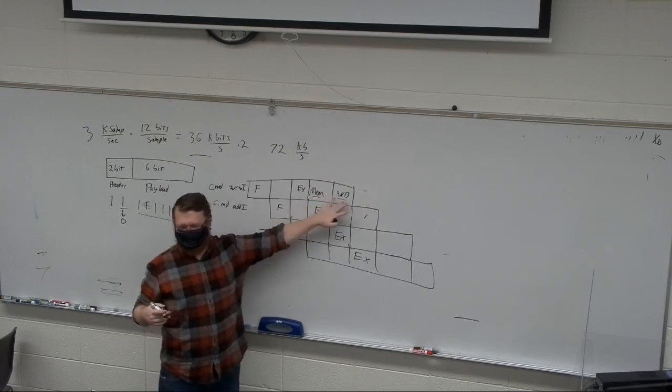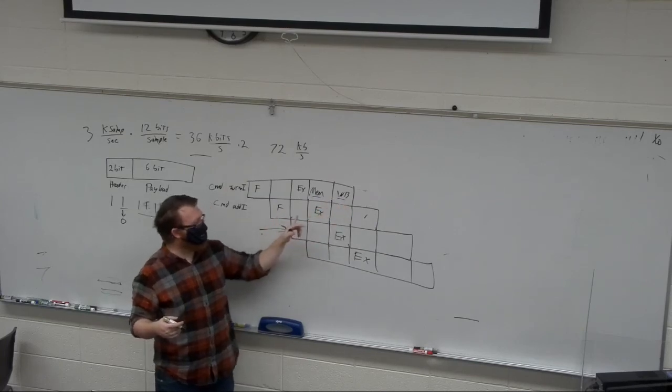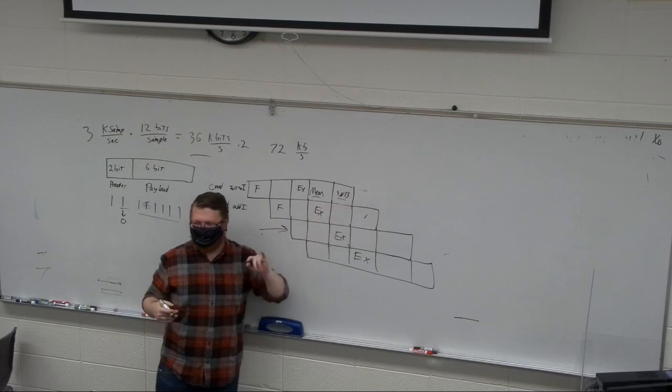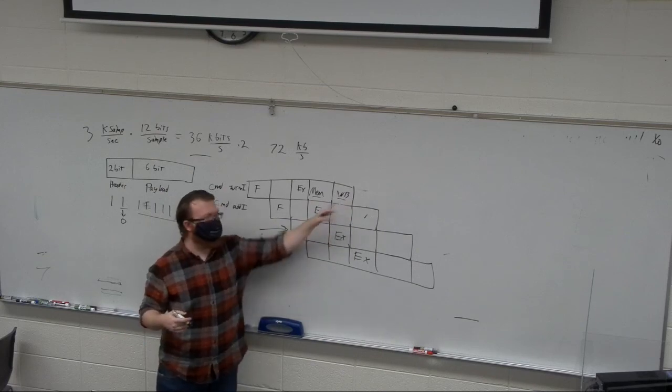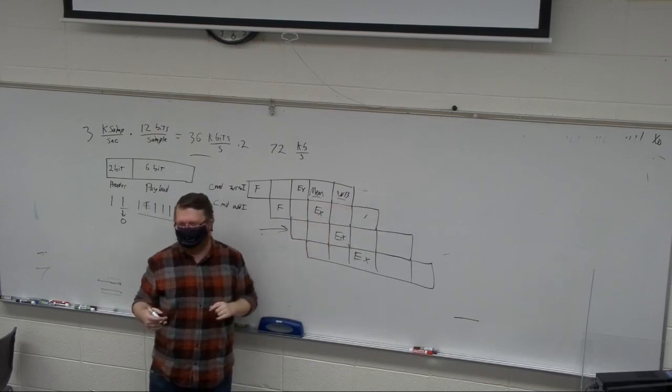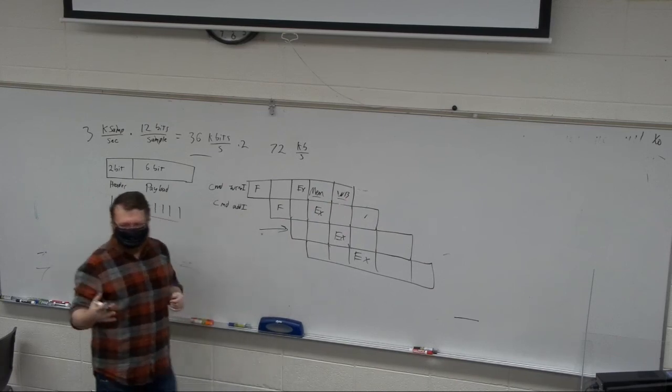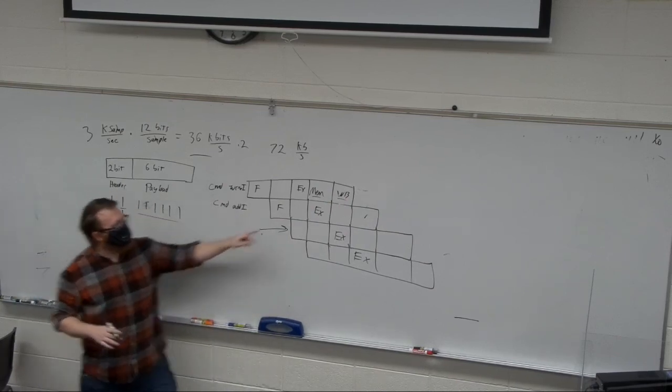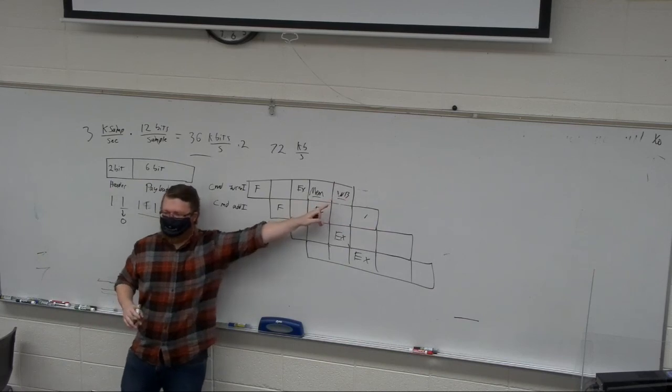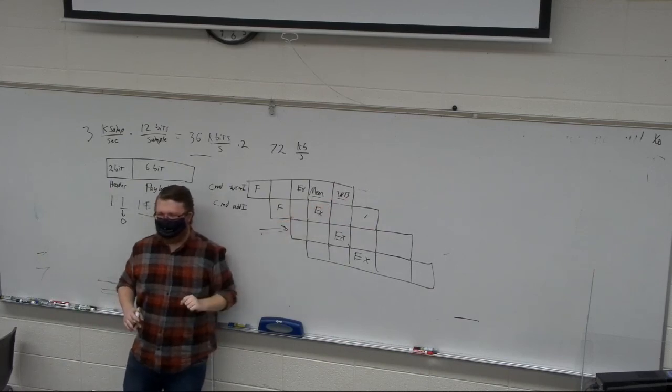But it doesn't really speed us up any, because it's not like this one can skip its memory and jump ahead into the slot where the memory would be, or the write back would be. It doesn't really speed us up any, but yeah, the memory might become available 1 clock cycle faster than the output register.